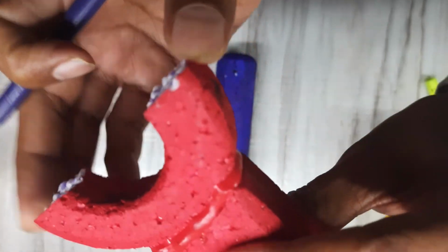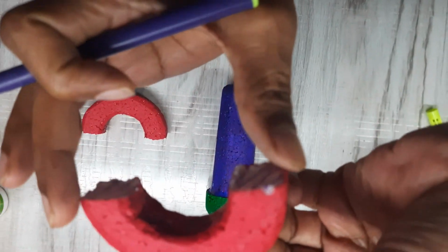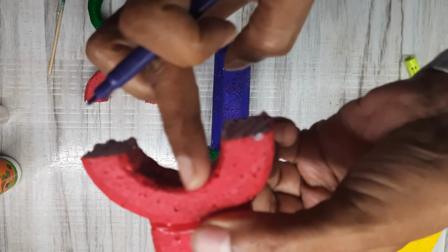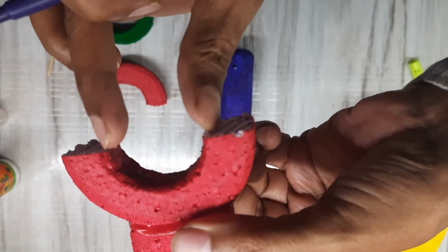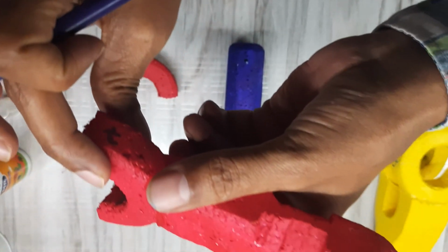You can see that T is the thickness of this single eye, and the outer diameter. How much is the outer diameter? That is D2, and the inner diameter is D1, and that's why we get (D2 minus D1) into T.